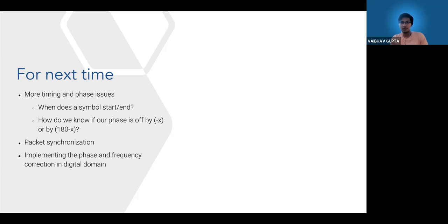And without being able to do that, even though we have a clearly defined symbol span, if both our microcontrollers aren't sampling at the same rates, or if we can't trust that they're sampling at the same rates, then we're no longer sure whether, let's say, I send only one, but at the other end I read that as two ones before the next bit of information comes around. So we'll talk about how to deal with something like that.